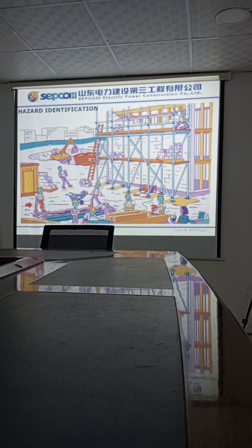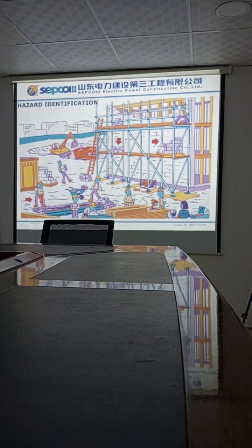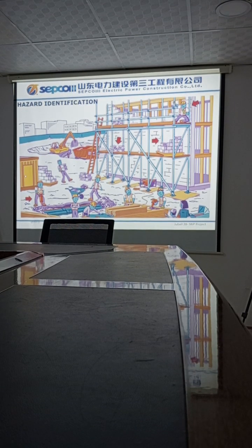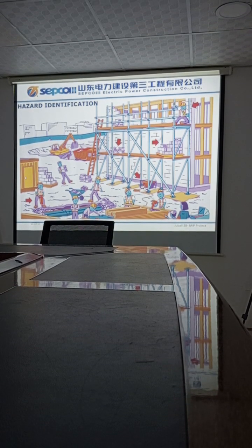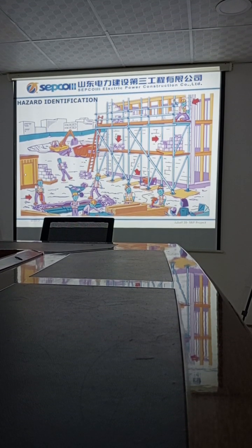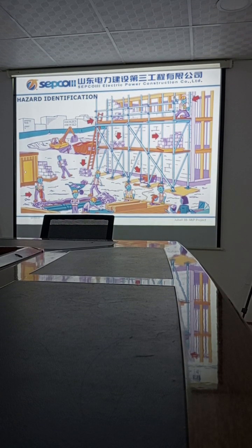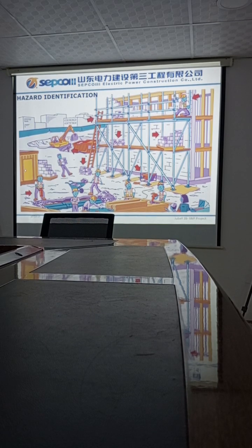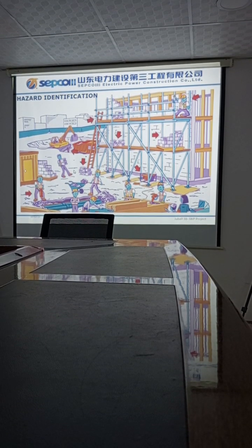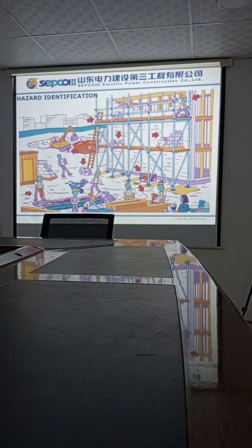The hazard will be this one: high noise, and material, because it can fall down and can collapse the scaffolding. This generator under the scaffold can cause a fire, blocking the access. See, no harness, these people are under a suspended load, and also equipment. Then they bring in the construction cables.